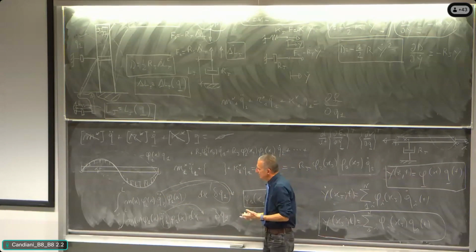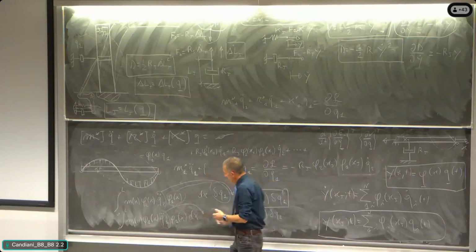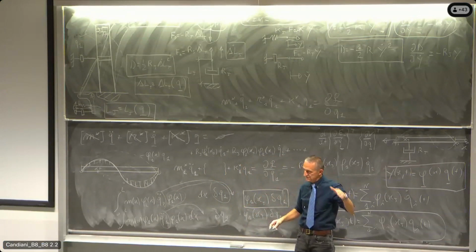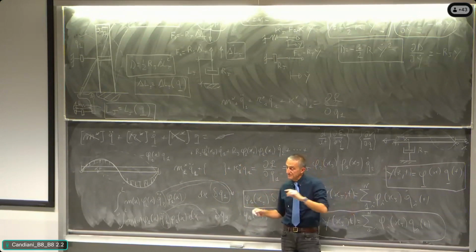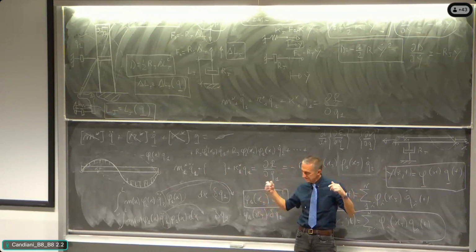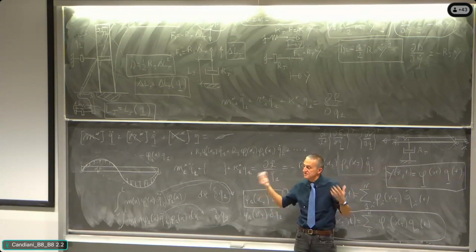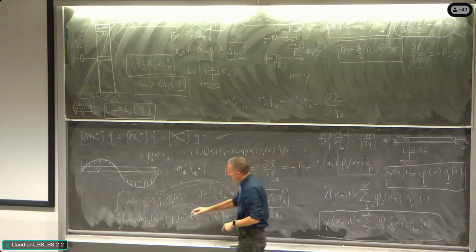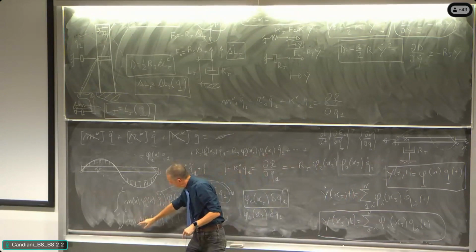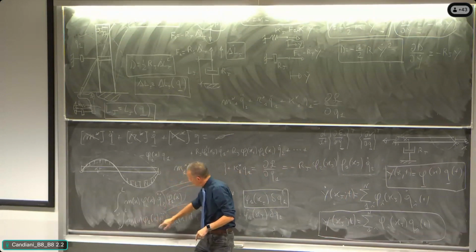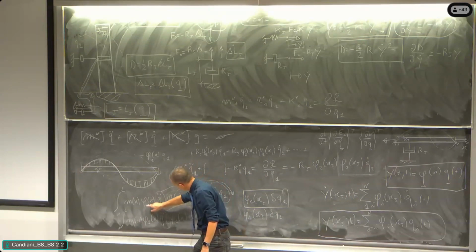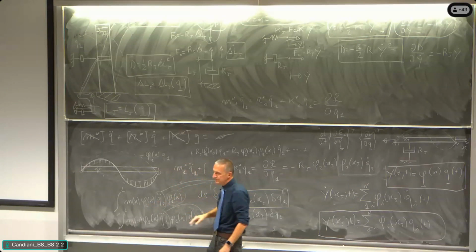But if we are working with the virtual displacement of the first mode over the distributed inertial force associated to the second, I go in the direction of writing the integral of the distribution of mass, one shape, the other shape. So the shape 2 times shape 1.